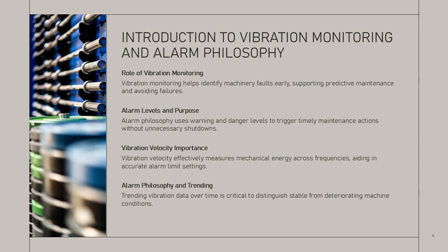Poorly defined alarms can result in alarm fatigue, unnecessary shutdowns, or, conversely, undetected faults. Therefore, alarm limits must be based on sound engineering principles, supported by standards, and validated through operational experience. Vibration velocity is particularly suitable for alarm setting because it correlates well with the mechanical energy transmitted to machine structures and foundations. Unlike displacement or acceleration alone, velocity provides a balanced sensitivity across a wide frequency range relevant to most